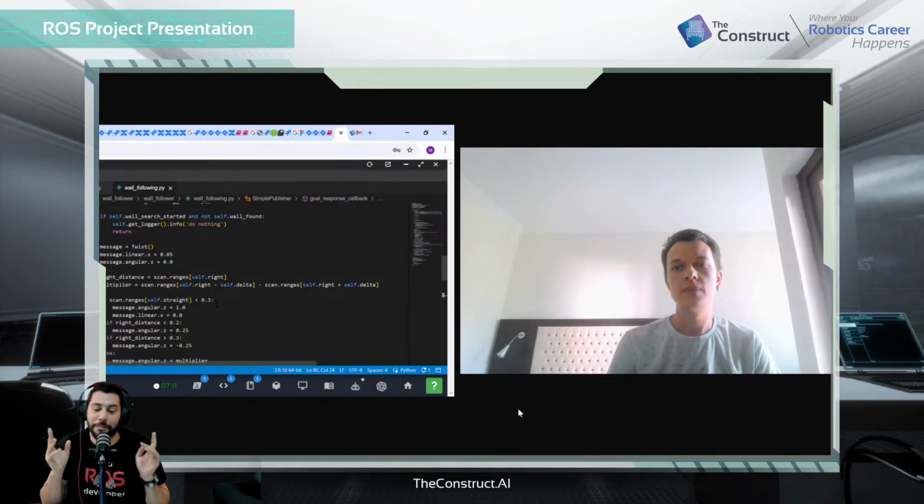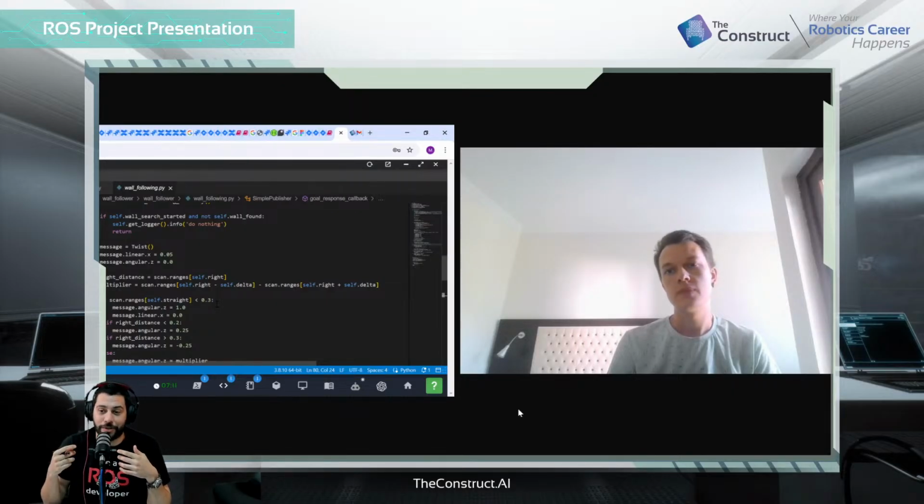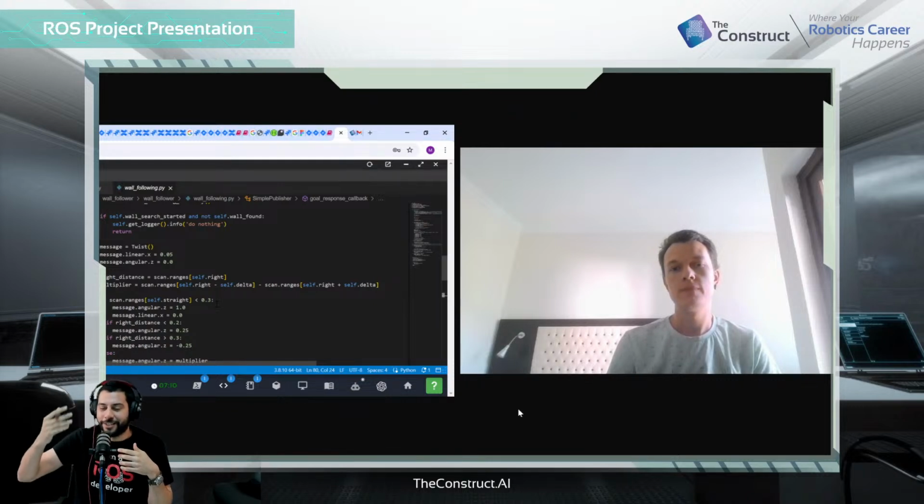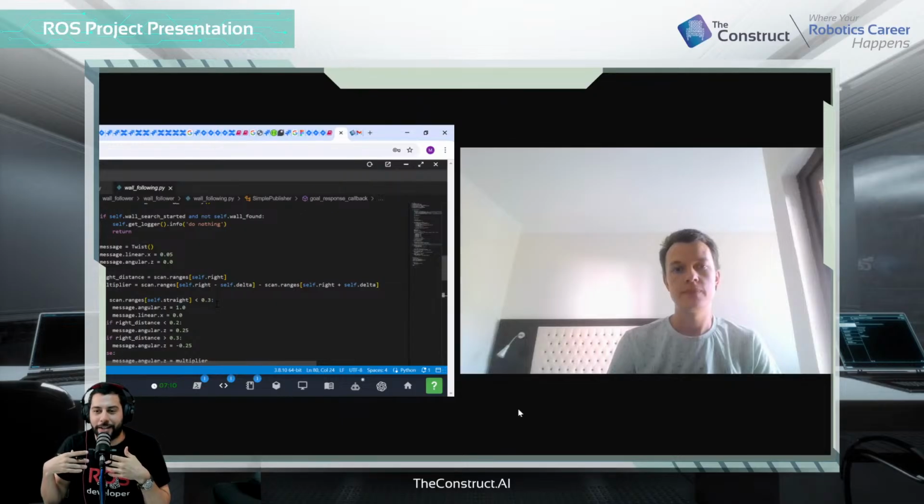And the reason for that, I believe, was that your laser callback hasn't completed yet by the time a new sensor message arrives. So for whatever reason, something in that callback can get stuck, and by the time the new message comes in, you might be too close. It's like, oh, time to correct, and it was too late. So that's one recommendation. You did it correctly in the service, so I encourage you to do that across the board for sensor callbacks.